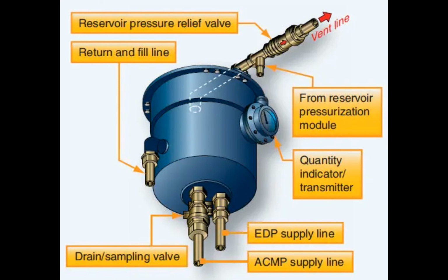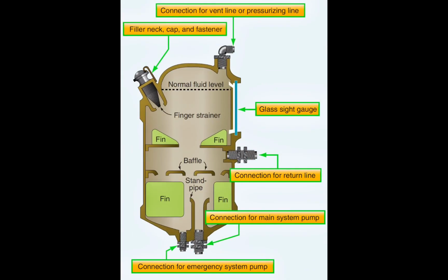What methods are used to pressurize hydraulic reservoirs? Pump, bleed air, small piston, aspirator. Variable displacement hydraulic pump. Engine bleed air. Pressure acting on a small piston inside the reservoir. Aspirator or venturi. Why are some hydraulic reservoirs pressurized? Ensure fluid flow to pump at high altitudes.